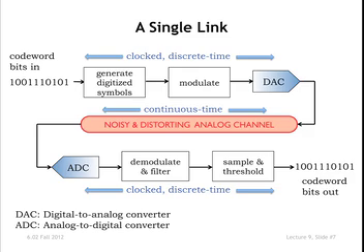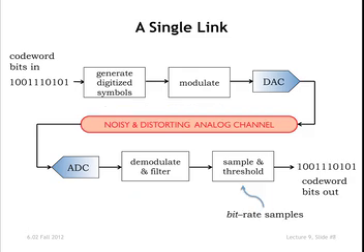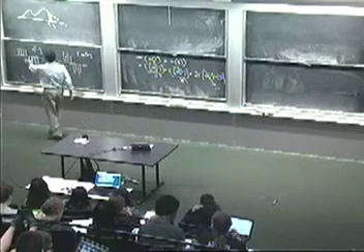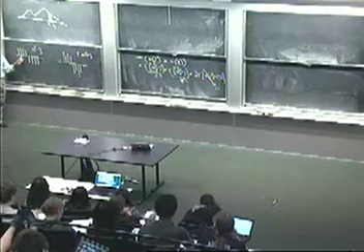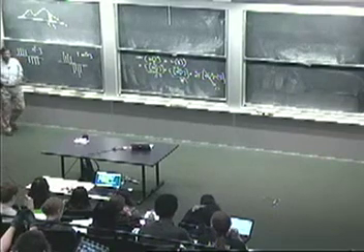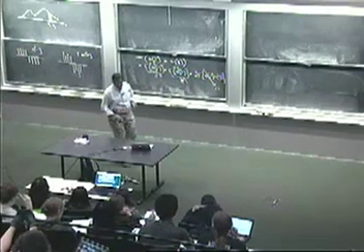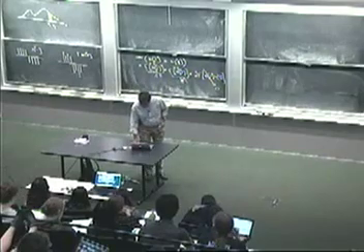Okay, then you're back to discrete time here. And actually, there are two clocks even there, because there's a particular clock that drives all of this signal processing, but then when you come to spitting out the bits, you're only going to spit out 1 bit per bit slot. So you've got many samples per bit slot, and then when you come all the way out, you're only going to report one number, a 1 or a 0 per bit slot. Okay, so there's all of this mixed together in the system.